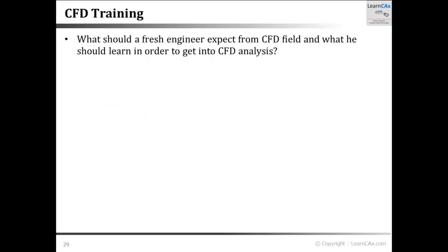So in short, during this particular session, we are almost at the end of this presentation. We have given you an introduction to the entire meshing process: what exactly grid or mesh generation means, how it fits into the CFD process, what its importance is, how we generate mesh using commercial CFD software, what the different mesh elements are, and how we use a mixture of mesh elements, as well as how we judge whether a mesh is appropriate for a CFD simulation or not. So this gave you an overall overview, or a summary, or just a short exposure to the entire meshing process.